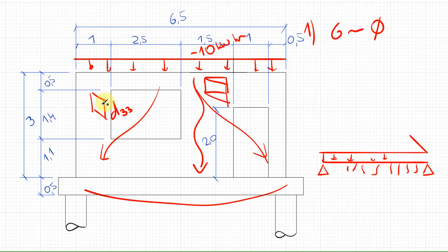We reduce the stiffness of the wall, but in 3D, if you look at the wall, and the wall is loaded by forces which are perpendicular to the wall, then the elasticity modulus for the shear will also be used. So if we reduce it to 0, then we also influence the bending of the wall.